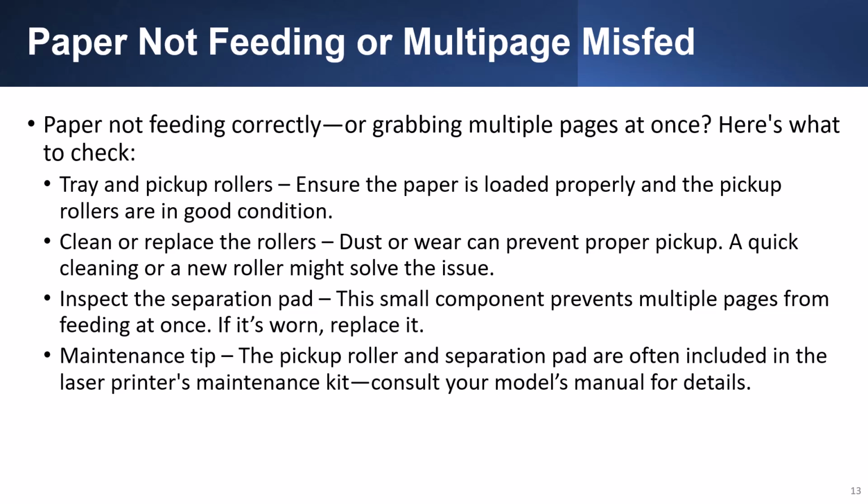Inspect the separation pad. This small component prevents multiple pages from feeding at once. If it's worn, replace it. Maintenance tip. The pickup roller and separation pad are often included in the laser printer's maintenance kit. Consult your model's manual for details.